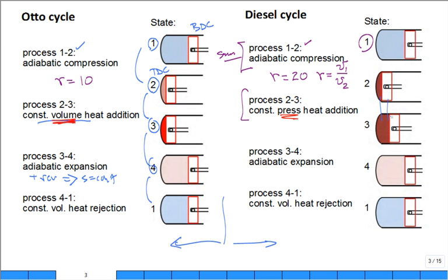All right, so here we're going to have a new parameter, R_C. This is very confusing. R for a ratio, just like R, the compression ratio, it's going to be a ratio of the volume when you stop the constant pressure heat addition divided by the volume when you started. That's called the cutoff ratio. Why do they call it the cutoff ratio? It's when the pressure is no longer constant as you are expanding. So it's like the fuel has been cut off.